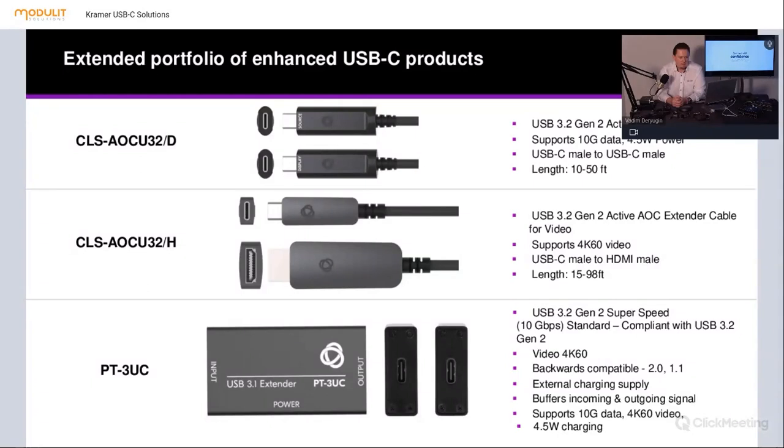I must say, don't make a mistake. If you are looking for a Type-C cable, and if you are going to use it as a multimedia transfer cable, you should notice that it is FF marked, full featured, because if you don't have this marking, the cable itself probably can be a data only cable, and you won't get any multimedia support.